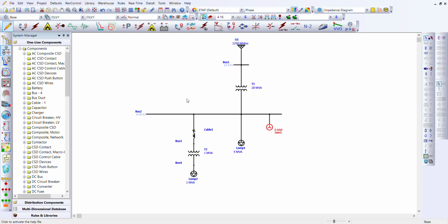Then for the gen category design, megawatts should be 5. Come here, click and put 5. Then Q max and Q min. For Q max, you click under it, and Q max should be 5. For Q min, let's put it at 1. And that's basically all you need to know about generators for now. Then we click OK. Let's take it down a little, and then we run the load flow again.